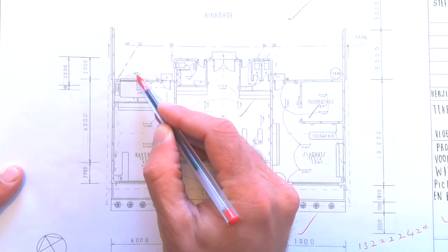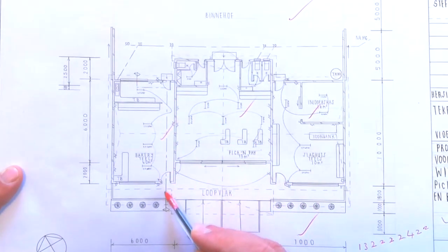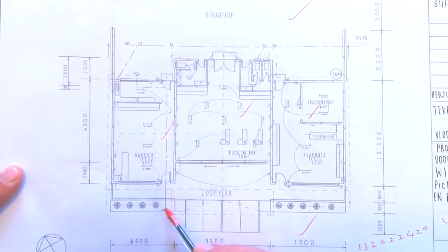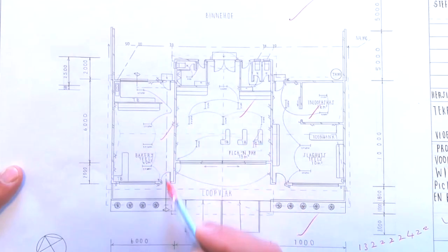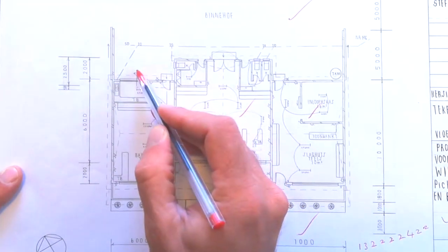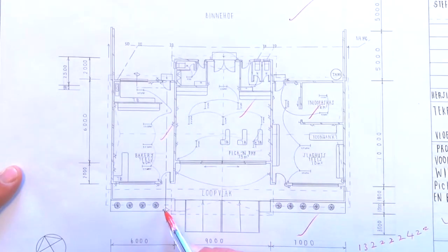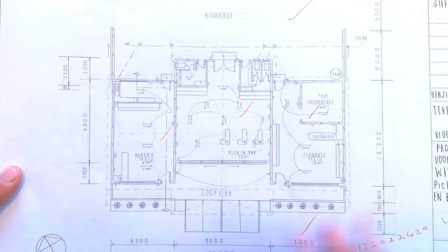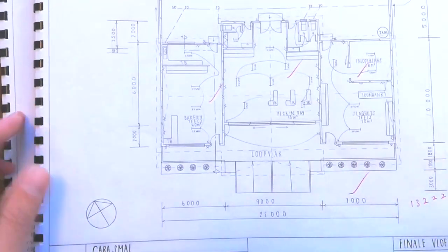In this case, it went through a window and then it kept straight, and there through a door, and they also had a similar veranda to yours on the outside. So your cutting plane, when you indicate that, it can be stepped like this to go through the required window and door, etc. Just make a note of that. Again, clearly labeled, and your north arrow on this side.